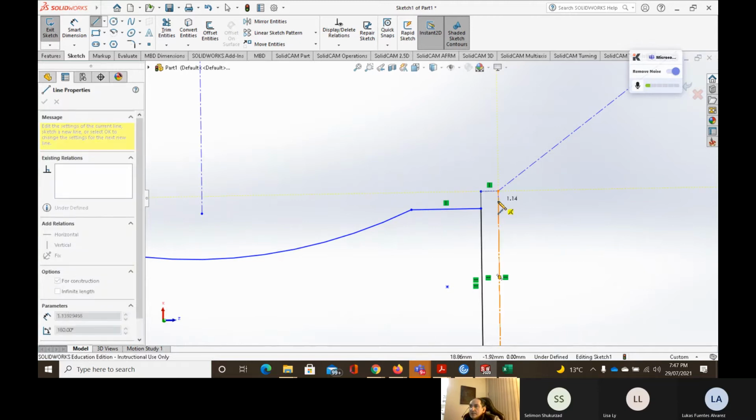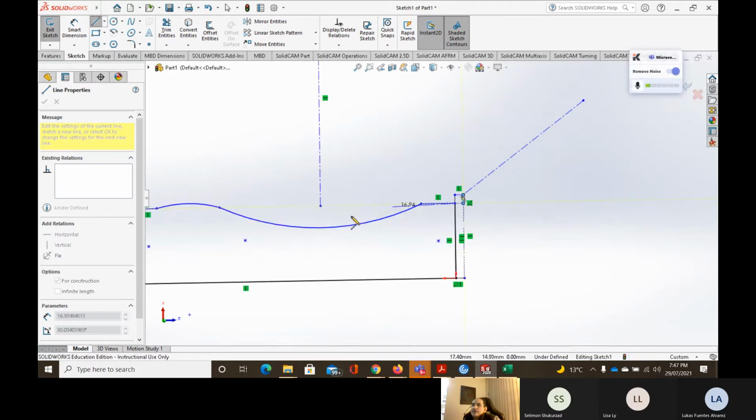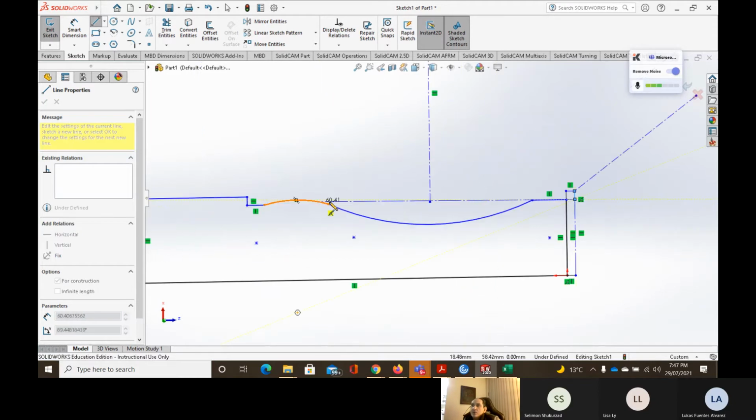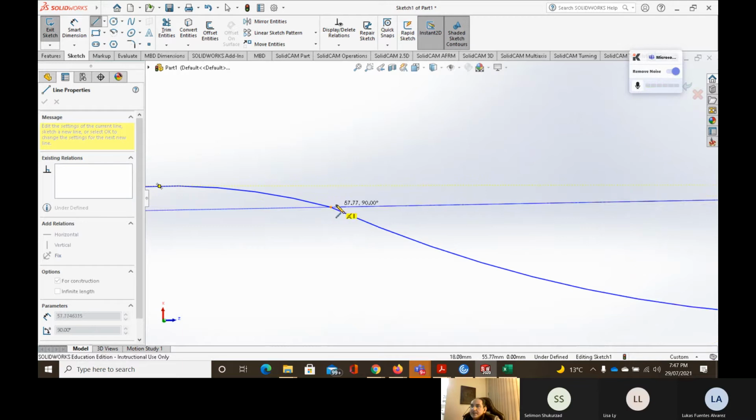I will go to this position, which is, for example, 1 millimeter depth, or let's make it 2 millimeter directly. This will be point number 6. Then I'm going to send my cutting tool all the way to here, to Z equal to -58.